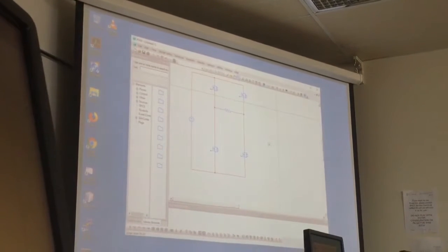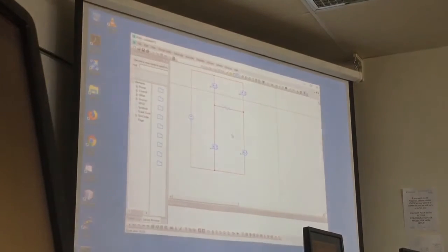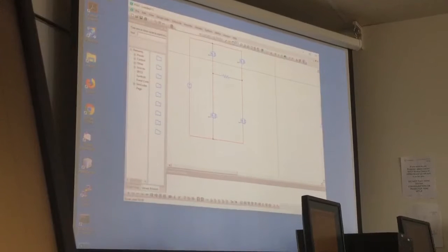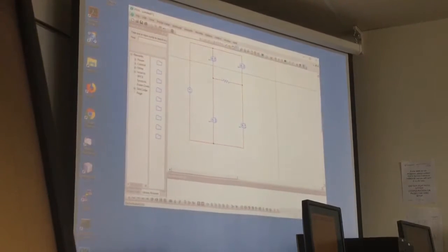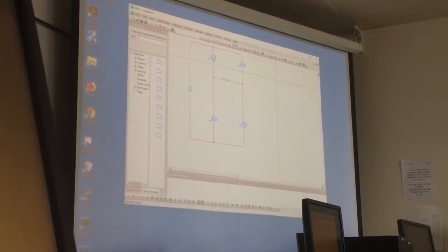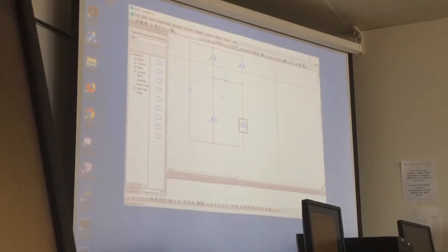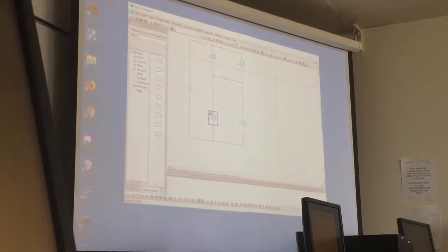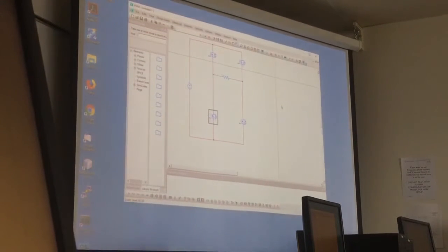So now we have our converter here. As I told you, we are going to switch the MOSFETs to get some voltage level in the load. If we switch this switch and this one together, we are going to have plus VDC on the load, okay? And if we switch this one and this one together, we have minus VDC. So we are getting an AC level on the load.